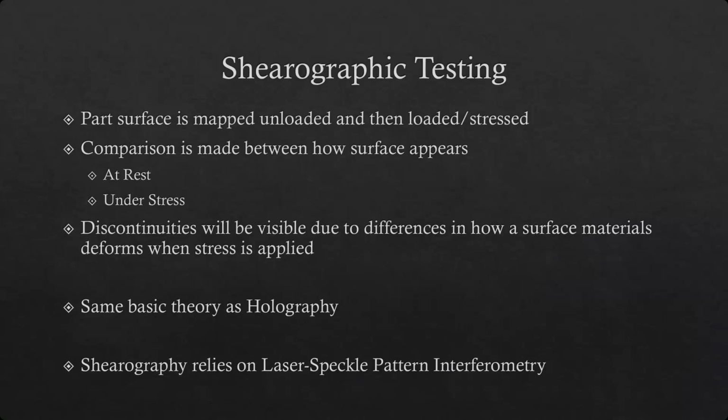But if you shine a light or a shadow from the side, you might be able to see different surfaces, right? Or different changes or undulations in the surface. This is kind of the same thing. If a surface is hard to see, it helps to magnify any changes in the surface by overlaying a speckle pattern while performing a holographic inspection.